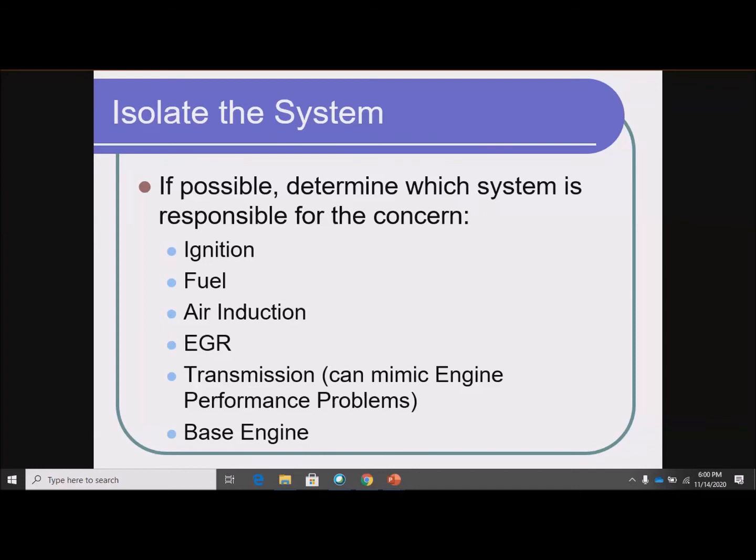Compression tends to be either good or bad. It doesn't really change with engine operating conditions, right? If a problem only happens cold or only happens hot, it's probably not something like a bent valve, right? That's going to be pretty consistent all the time. But if it's an ignition misfire, a bad coil, a weak coil, that might happen under load, and not happen at idle, decel, or cruise.